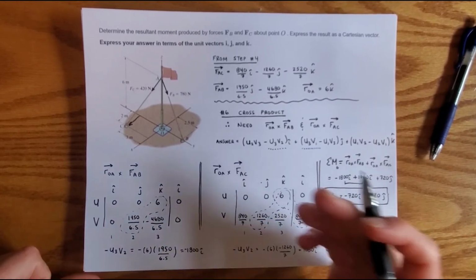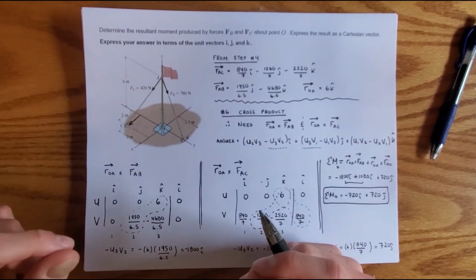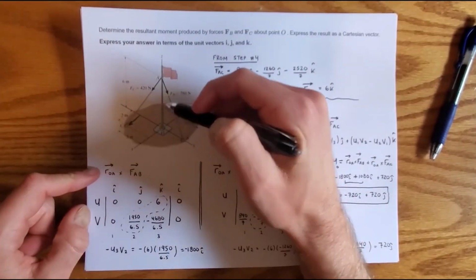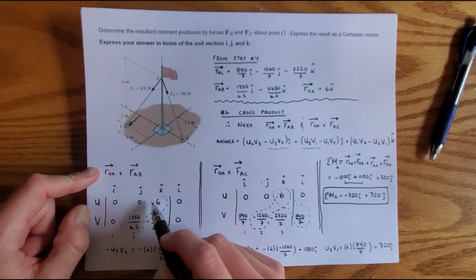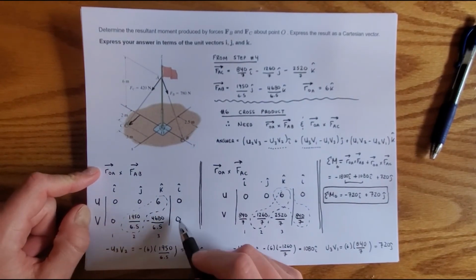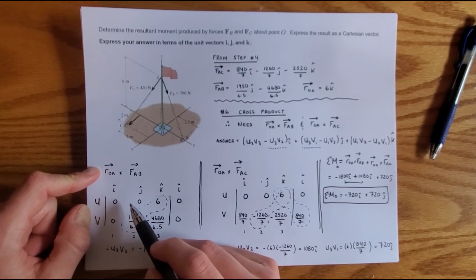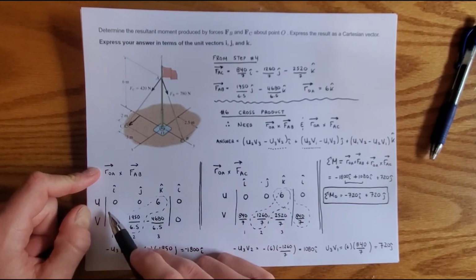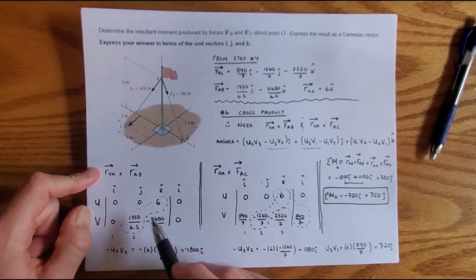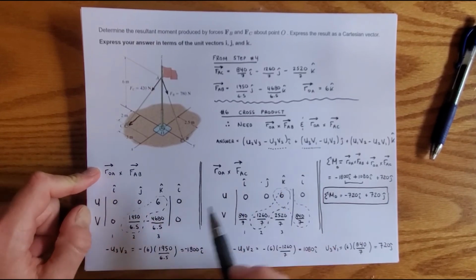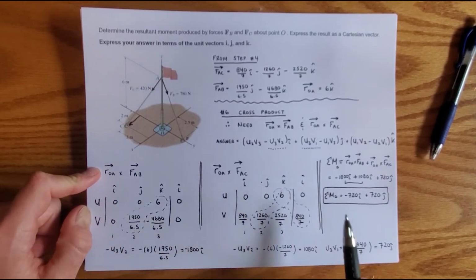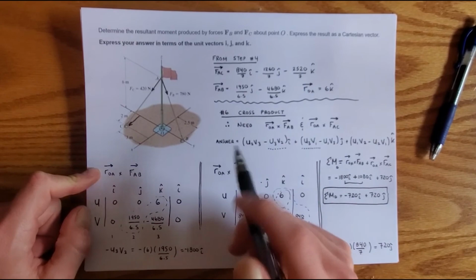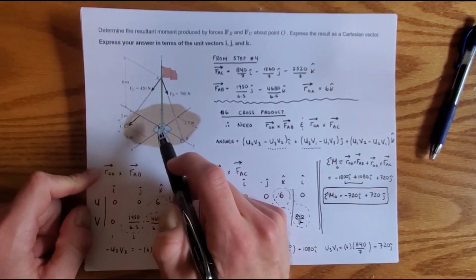Now, in this particular example, as you saw just a page ago, I was able to figure things out just with common sense. And the reason why that's the case is because our moment arm was only a z moment arm, which is very simple. It's going straight up and down. So it's pretty clear that only certain forces, which are basically forces in the y and the x, are going to cause moments about a moment arm in the z. But in the future, it's very possible that your moment arm might have a value in the I and the J, in which case it's going to be basically impossible to do unless you set up the cross products in such a way. And there you go. That's how you do cross product to solve for the moments caused by three-dimensional forces about a three-dimensional moment arm.